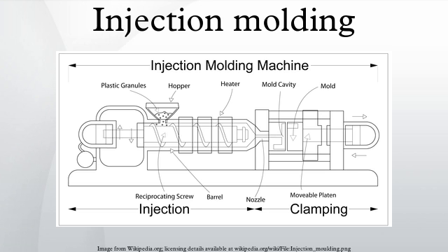When the weight of the part does not change, we then know that the gate has frozen and no more material is injected into the part. Gate solidification time is important, as it determines cycle time and the quality and consistency of the product, which itself is an important issue in the economics of the production process. Holding pressure is increased until the parts are free of sinks and part weight has been achieved.